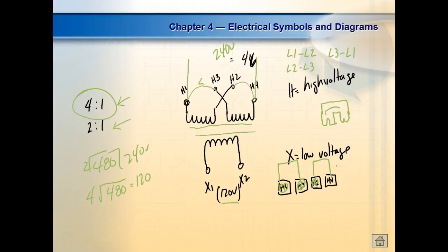So right now, if you go up there, you'd see a jumper between H1 and H3, and a jumper between H2 and H4. And then, of course, H1 and H2 is going to go back over to two of the lines. And y'all need to stagger those, right? We know how to hook them up. So some of y'all need to use what? L1, L2, and we'll figure out how we go down there. The next group needs to probably use L2, L3. The other one needs to do L1, L3, and then we'll start the sequence over. Because what we need to try to do is balance the load on our three-phase panel box out in the hall.